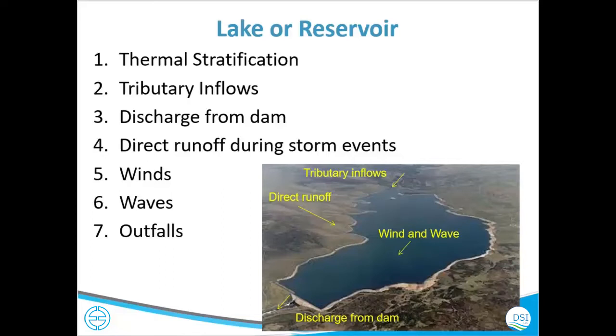If you have money or time, you can do hydrologic modeling, create different subbasins, and then calculate the flows from each subbasin and then tie it to the boundaries in EFDC. But usually we are on a time crunch, and we need to give them an update on what's going on before we move to phase 2, right?